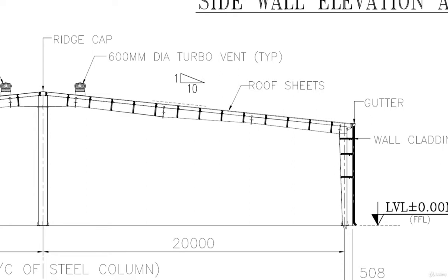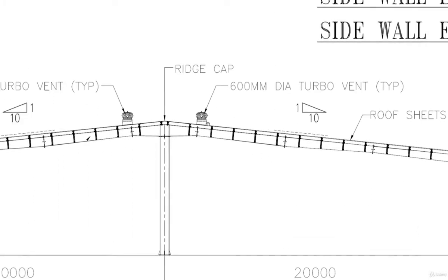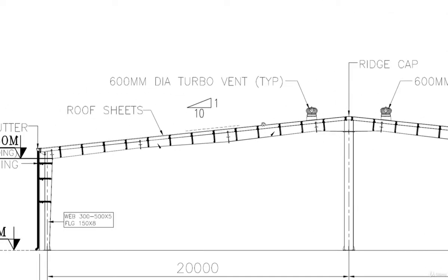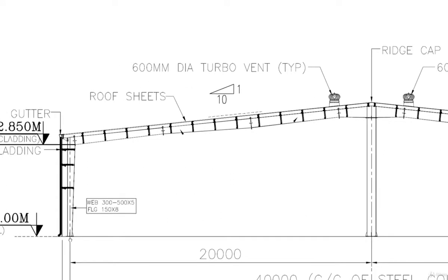If we draw the bending moment diagram, which we will see in the results lecture, you will see that it is somewhat like this. The bending moment is maximum here on the top, then it comes to the bottom here, then again goes to the top, again to the bottom, again to the top, and it reduces to 0 at the bottom. Why does it reduce to 0? Because the bottom conditions of PEB sheds are preferably pinned.